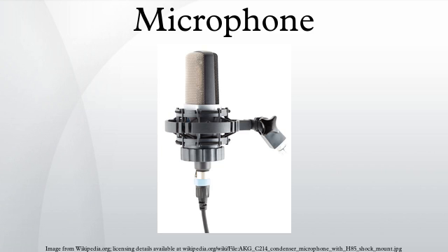Components: the sensitive transducer element of a microphone is called its element or capsule. Except in thermophone-based microphones, sound is first converted to mechanical motion by means of a diaphragm, the motion of which is then converted to an electrical signal. A complete microphone also includes a housing, some means of bringing the signal from the element to other equipment, and often an electronic circuit to adapt the output of the capsule to the equipment being driven. A wireless microphone contains a radio transmitter.